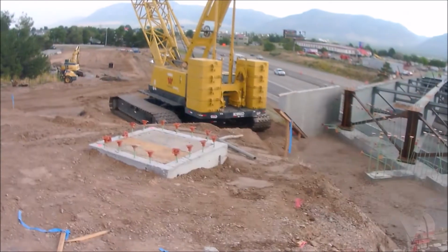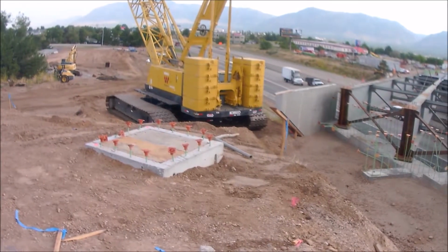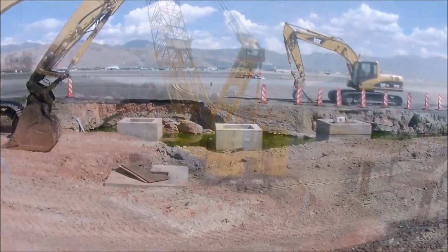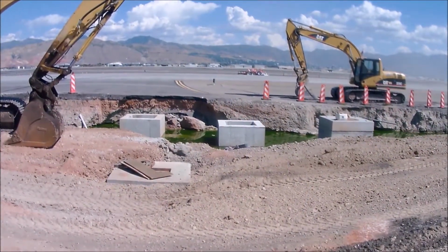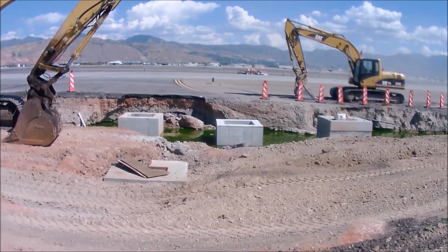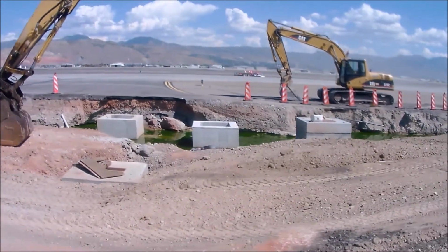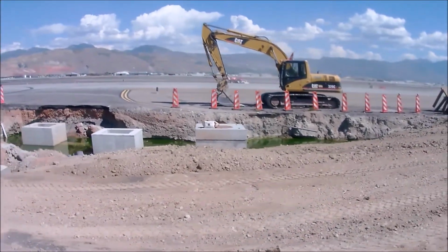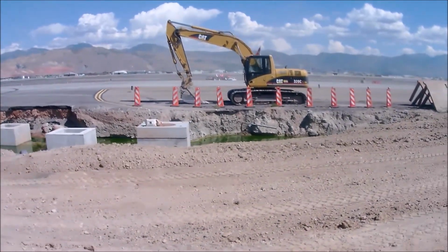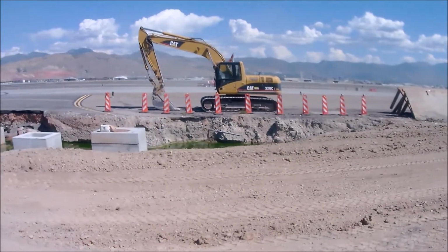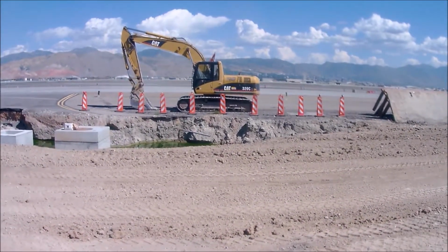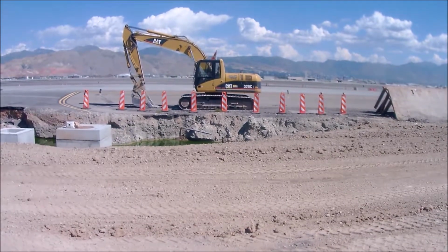Permit-required confined spaces meet the first 3 parts plus have one of the following hazards: bad atmosphere, engulfment hazard, entanglement hazard, sloped sides or other difficult egress features, explosion hazard. Controls include confined space training, supervisor training, confined space permitting, lockout, tagout, and confined space authorization.